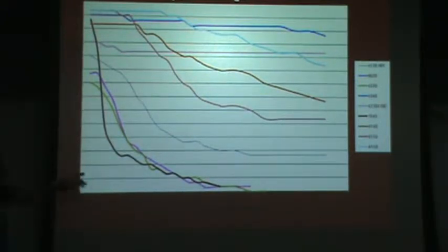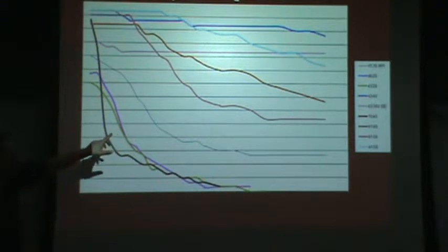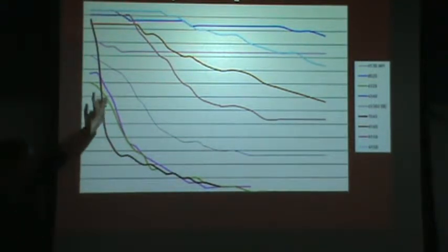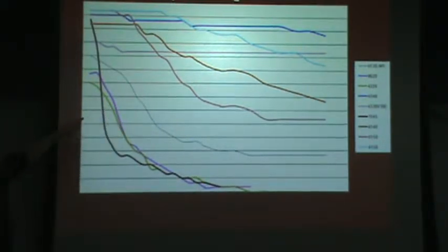And we can see that if you look at this brown line here, this is 1045, and if we compare that to, say, the dark blue line at the top, which is 4340, you can see the 4340 has a line that's not exactly horizontal, but almost, whereas the 1045 drops way off. But if you look at J1, they're not identical, but they're very similar. That's because carbon is the primary actor at that test position.